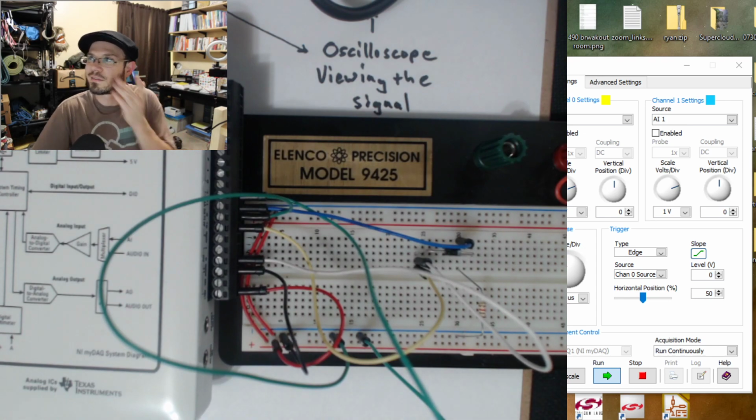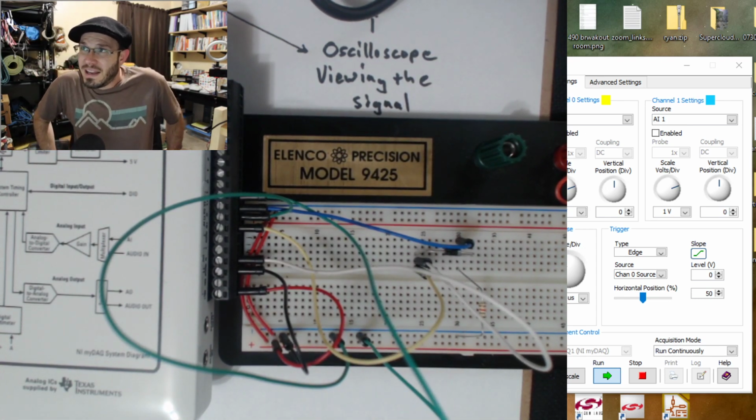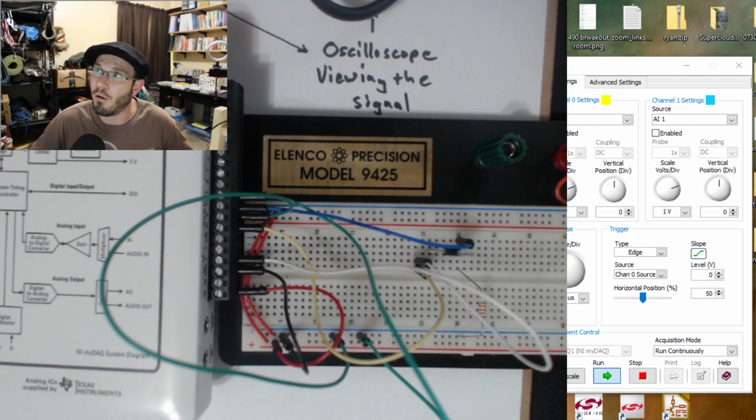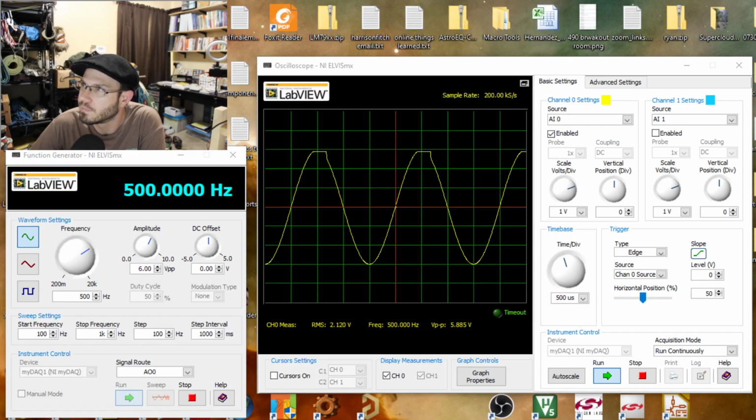Okay, there we go. So now my channel 2 should be measuring the output of this device under test, this series diode clipper circuit. So let's go back over to the software view, and let's go ahead and turn on our channel 2. Okay.